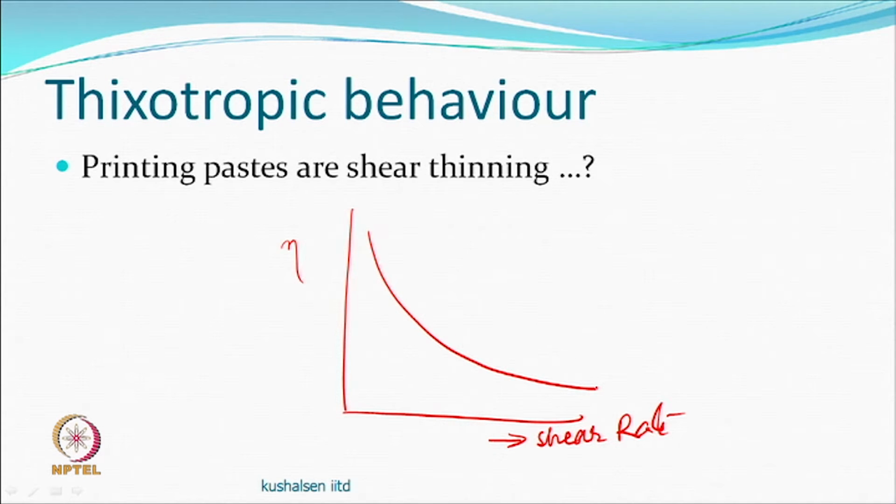This phenomenon is seen with the printing paste. This phenomenon is seen in polymers which are melt spun. It is seen in polymers which are wet spun. And why it is important is, if because of the shear, this viscosity does not go down, the amount of force required to push it through the holes or pores will be very high.